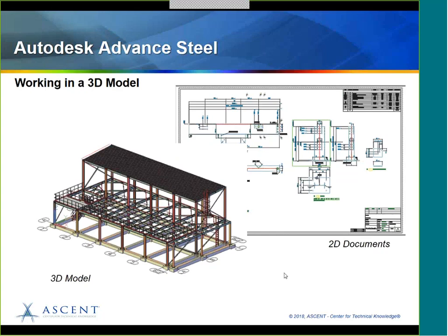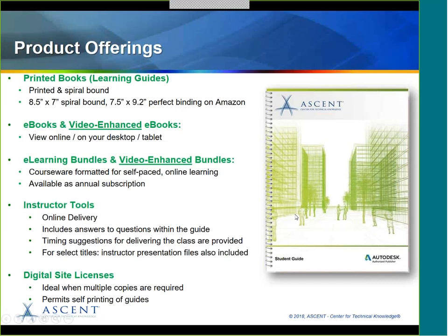So I did what I hoped I was going to. I created a 3D model of a steel structure. We added connections using the connection manager, and then extracted 2D drawings from the model and reviewed the detailed drawings using the document manager. So I know that was a whirlwind trip, like I said, but let me just pass